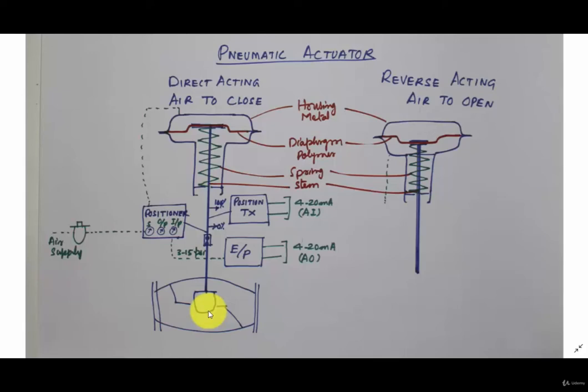Because of process pressure, it develops a very high force pushing the plug up and up. So against this process pressure, the actuator has to produce more pressure to push the plug down. That's why you require a higher pressure than this. Only 3 to 15 is not sufficient. This is a signal, okay. But more than this signal, we need an amplified pneumatic signal to operate the actuator.